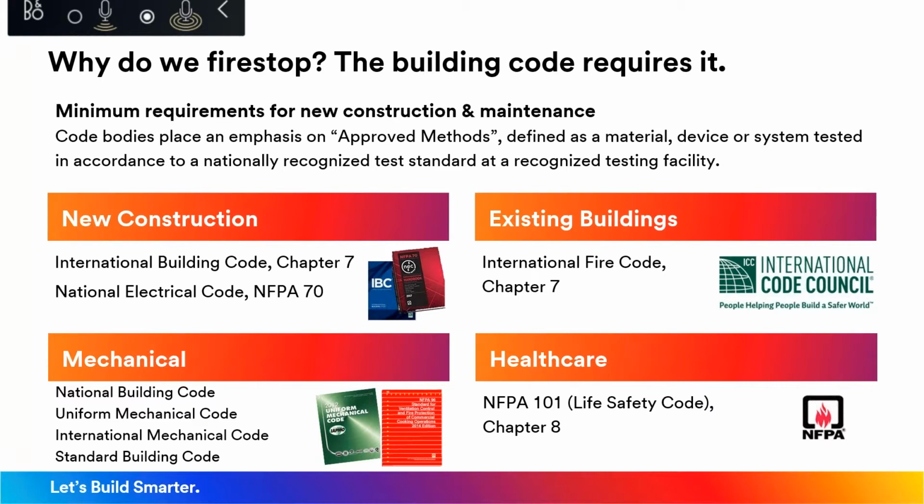Okay, so fire protection is all required per code. We're not doing it for our health, but it's all per the local jurisdictions and or industry code requirements. So fire stop is required once you've penetrated a substrate. It's a code requirement.